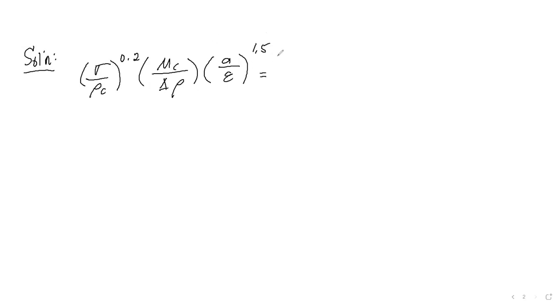Okay, so with this, we will now try to substitute the available information and get the others on the appropriate table. So for the dyne per centimeter value, we have 25 dyne per centimeter. It has to be converted to pound mass per hour squared because dyne per centimeter is an SI unit, whereas pound mass per hour squared is used in English. And our problem is using English units.